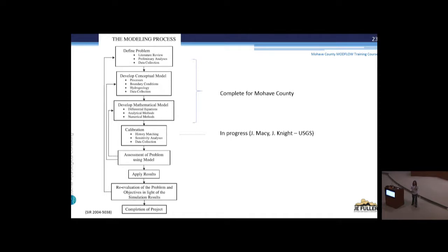So let's say you've got a region of conductivity that you don't really understand. You don't know how the conductivity in this basin works. Is it really high? Is it really low? You think it's something like the next basin over, but maybe it's not. Anyway, the calibration process is all about trying to come up with a conductivity distribution for the whole model area. So areas of the alluvium have one kind of conductivity, areas of the mountains have another kind. But you want to devise some explanation for how water moves through the system in a way that makes sense and that matches historical observations.